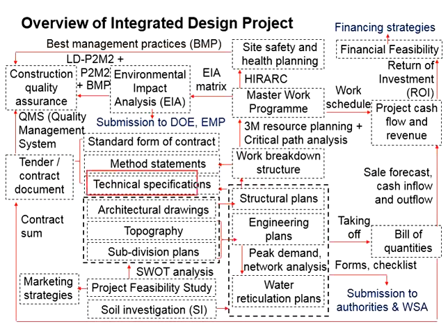Now, where do you get the technical specifications? You will need to refer to the design by the engineers. How about the method statements? This can be based on the work breakdown structure. What are the construction tasks to be carried out? Then produce statements explaining how each project task is to be carried out, in terms of the sequence as well as the quality expected from the relevant tasks. This brings the necessity to work out the work breakdown structure.